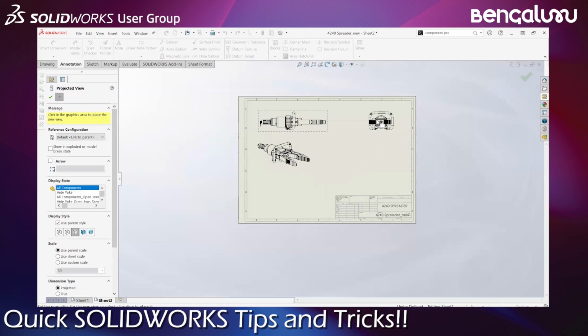Now if you want to break alignment, generally what we do is we place the view and right click and say break alignment. But rather, before placing the view, you can just hold the control key. This makes sure that alignment is broken. It need not be in the same line. But once I release the control key, you see that it aligns itself to that particular alignment, right? So again, I hold control and drag it. So now I can place it.